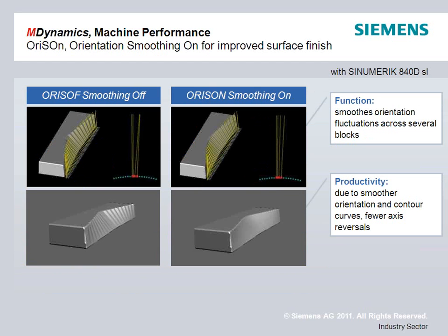We also have a new function for 5-axis that is becoming very usable. We call it orientation smoothing. This is a 5-axis function only, and the purpose of orientation smoothing is like the compressor we have to deal with when we have short block programs and there's a few points that are bouncing around and not quite a nice smooth surface. We can compress those just as an XYZ curve, make them a very, very smooth curve, and handle it internally as a high-order curve.